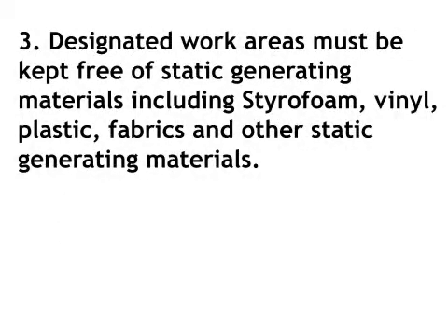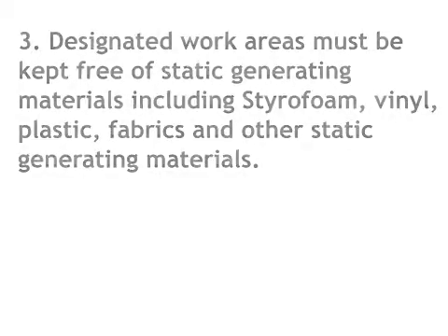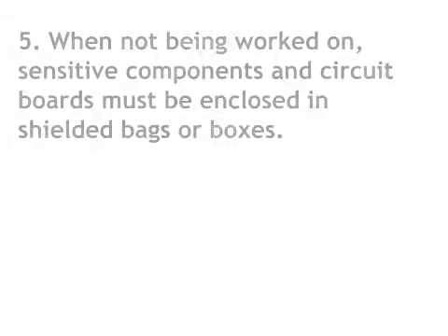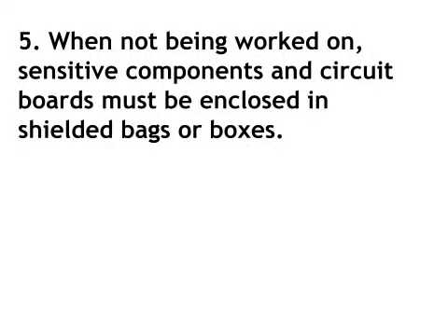3. Designated work areas must be kept free of static generating materials, including styrofoam, vinyl, plastic, fabrics, and other static generating materials. 4. Work areas must be kept clean and neat. To prevent contamination of circuit board assemblies, there must be no eating or smoking within the work area. 5. When not being worked on, sensitive components and circuit boards must be enclosed in shielded bags or boxes.